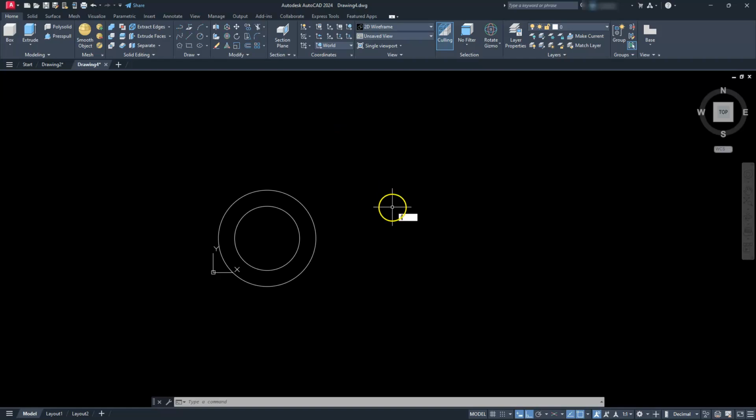So I'll go with line, enter, so L, enter. I'll select this center, and then I'll come this direction, right? My ortho is on, as long as I'm pointing this direction, I'll type in 100. Go ahead and hit escape.